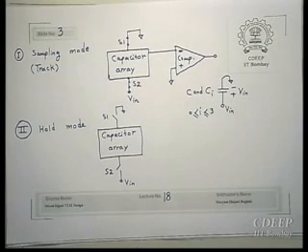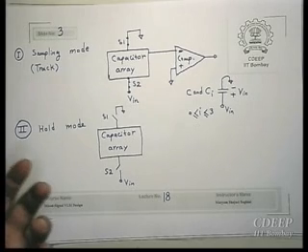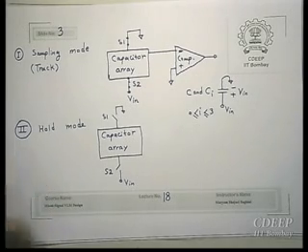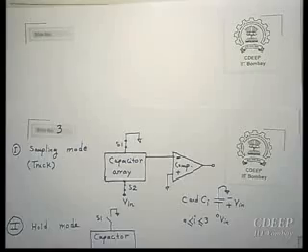Okay, so now we will go in the hold mode. In the hold mode everything is open, therefore nothing special is done. So now what we want to do is start to generate reference levels, right? To generate reference levels, we will go again capacitor by capacitor, same as before. So now we will go with the redistribution.